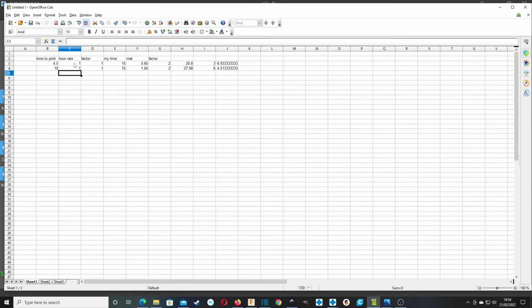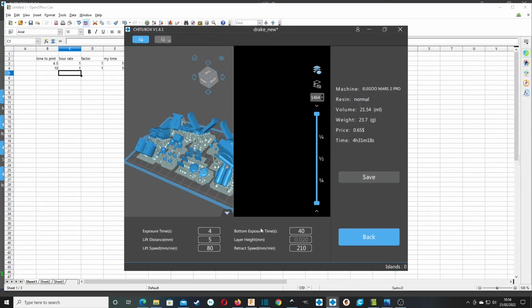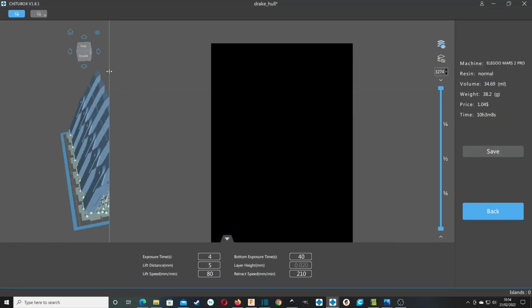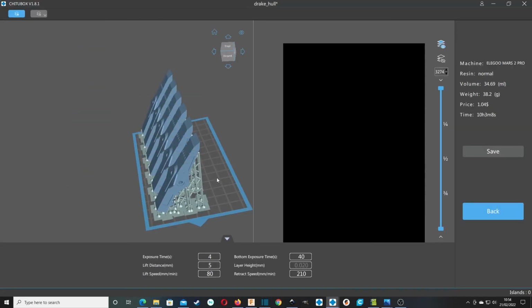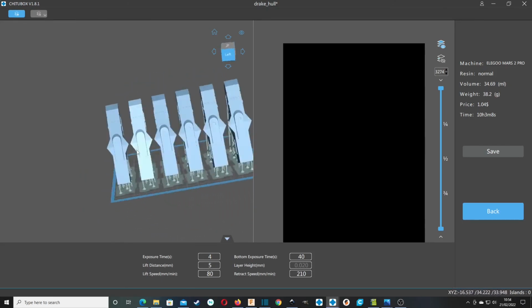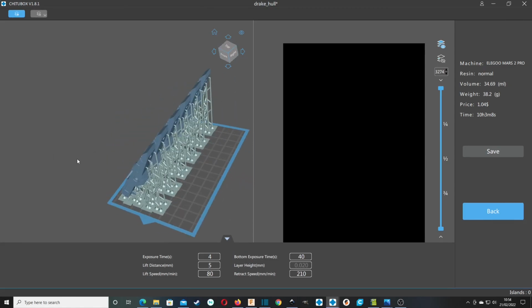This is the sort of thing you can do to save yourself a bit of money by asking for multiple prints on the same print. And this is what we're doing with batch printing, when you see someone on eBay and Etsy selling multiple things. We're making multiple of them on the same print, or we're breaking the small parts off onto their own print, and then putting the taller items onto another. Another way you can do this is to lay these all flat, but to get the best quality, I do it this way. So, yeah. Thank you for listening.